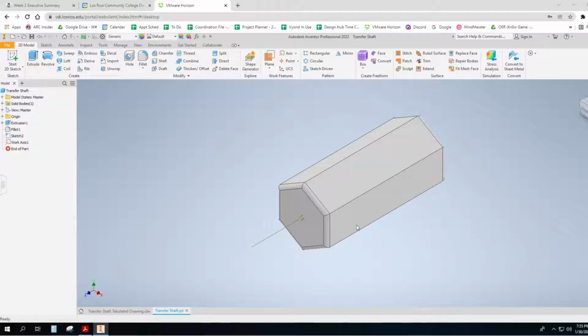So we'd like to take care of that with something called parameters, where we can change this length easily and quickly and then develop the manufacturing file that's needed. And in addition, there's some differences between the size of the hex depending on what material it is and how it's being manufactured. So this becomes what's called a base file that is used to create many different variations of essentially the same thing. They're all exactly alike, but just a little bit different.